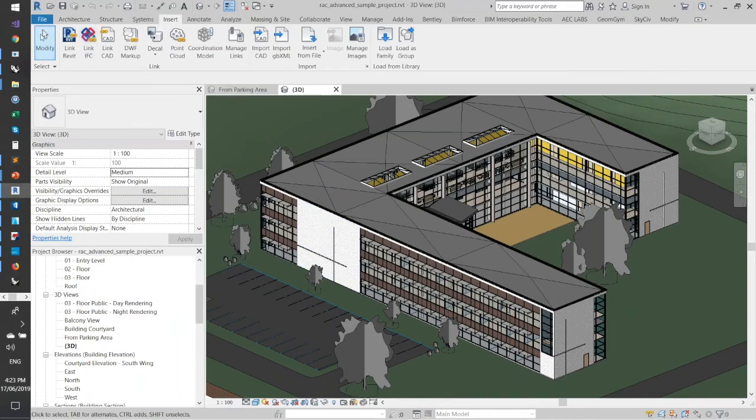Two things, I guess, quickly, or one thing on when actually consuming IFC with Revit. It doesn't import the model relative to shared coordinates. So if you're using an authoring application like 12D, you probably need to set a zero base point or manually change the base point in the IFC file so that the extents of the model don't come too far out of origin, or you might get strange displays of elements or missing elements that appear as part of that process.